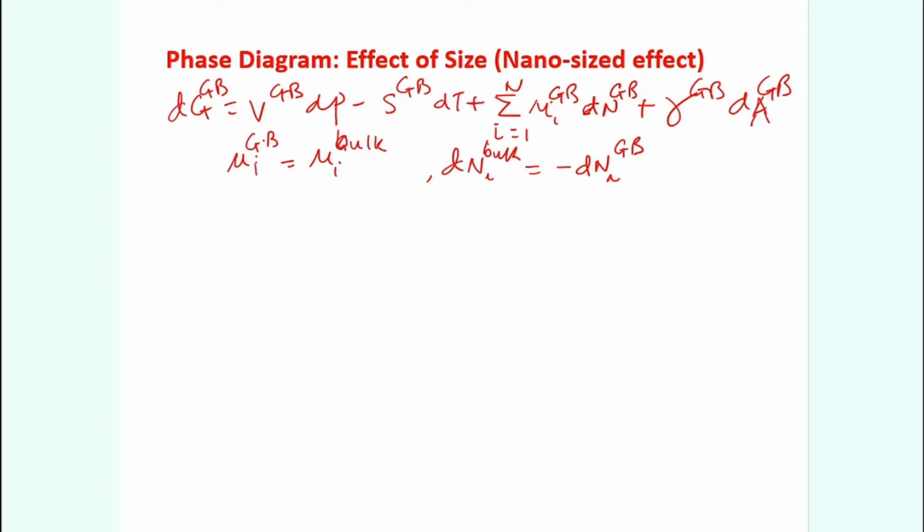If you transfer from one place to another, the place from where you are transferring loses, and the place where it is getting transferred gains. So if it is transferred from grain to grain boundary, that is what happens. It can also happen from grain boundary to grain, correct? If a grain boundary is consumed, then this will not happen. If the grain boundaries are created, then other things will happen. Nonetheless, this vital mass transport condition has to be satisfied.